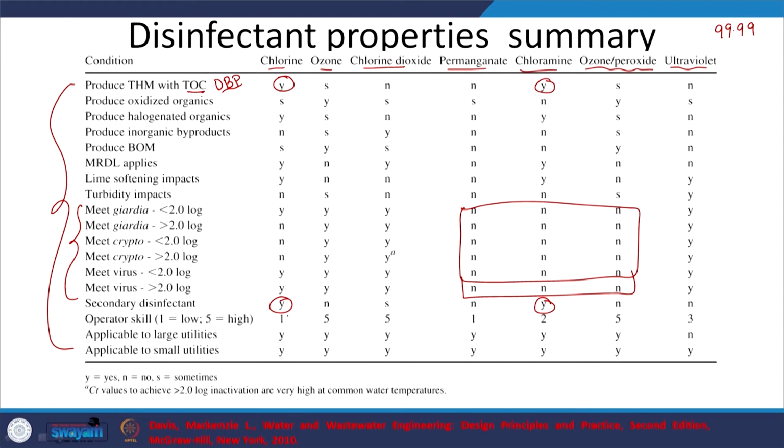If I add too much chlorine, I know these toxic disinfection byproducts will be formed. So it's a trade-off how I want to go about it. But sometimes you can have ozone to kill the microbes and the trace organics, and then add some chlorine so that the DBP concentration will be less, but you will have enough residual chlorine available. So let's dig deeper into this aspect.